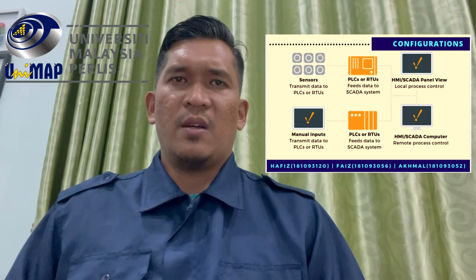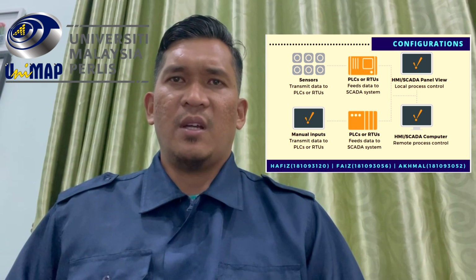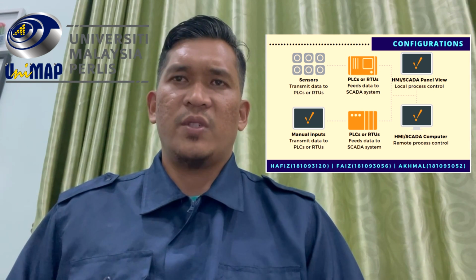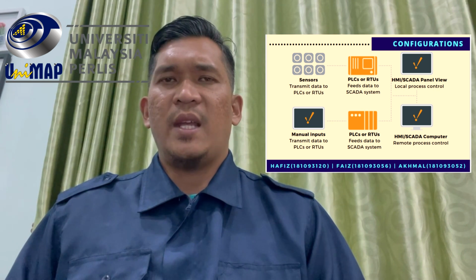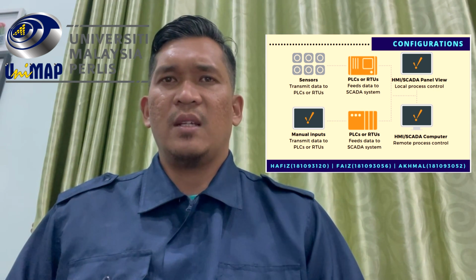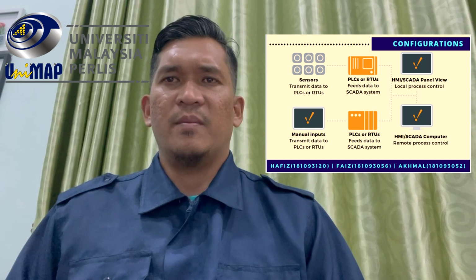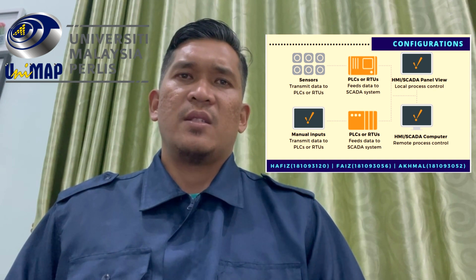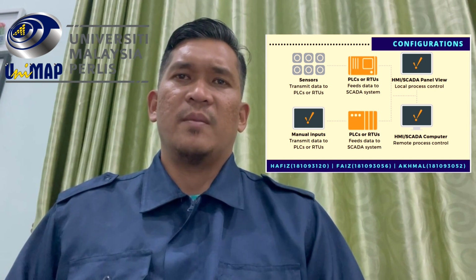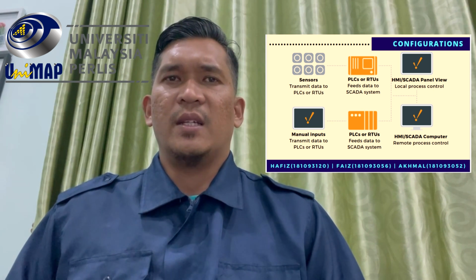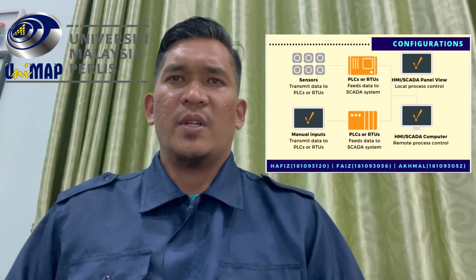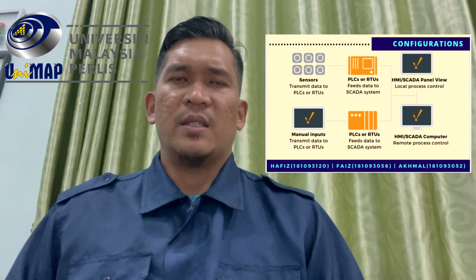In this configuration, any combination of components may be used to support the load. This gives more flexibility than separating components into a redundant system, but it requires shared control of all components, making the PLC a possible single point of failure. These are the steps to configure SCADA system.